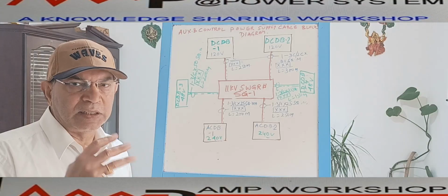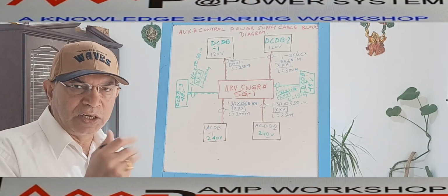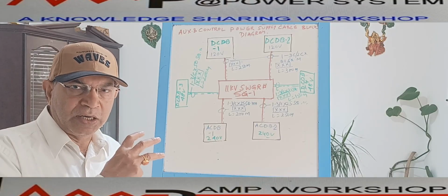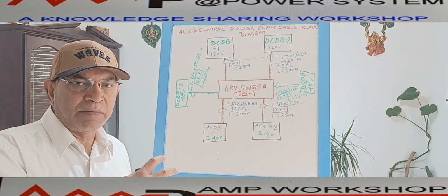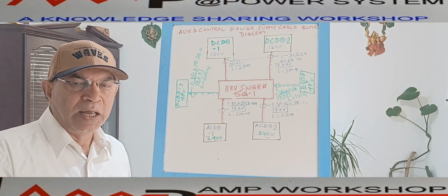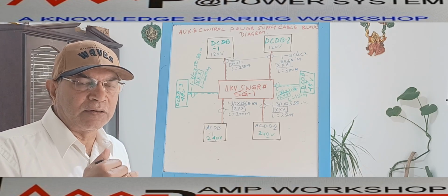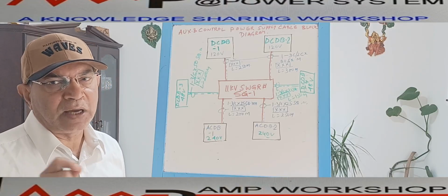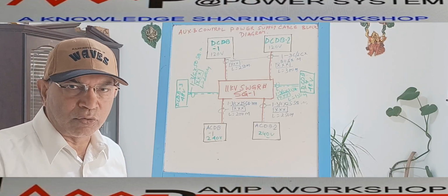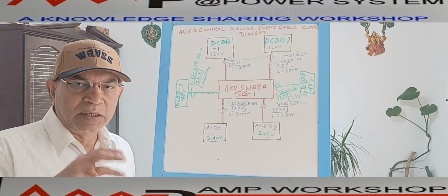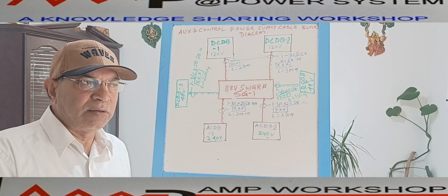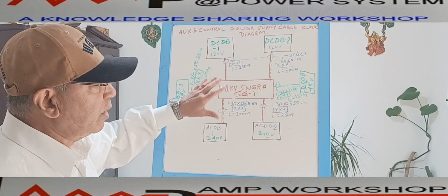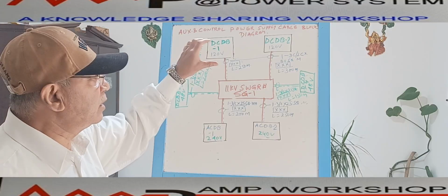You know, the battery DC supply is coming in the plant through the DC UPS, or you may call it a battery charger. There is a backup battery and there is a charger. That charger takes the AC supply from the system, converts it to DC supply, and that DC supply is also backed up by the battery. The total DC is coming to a DC distribution board. From the DC distribution board, various feeders are going to the various equipment. So our connection point with the switchgear for the DC supply is the DC DB.